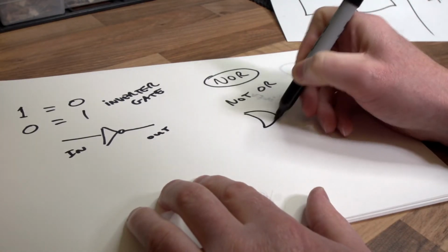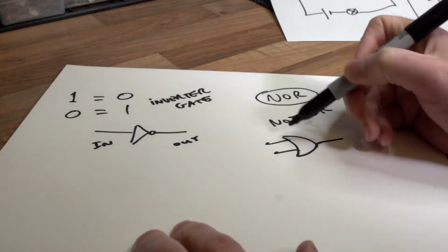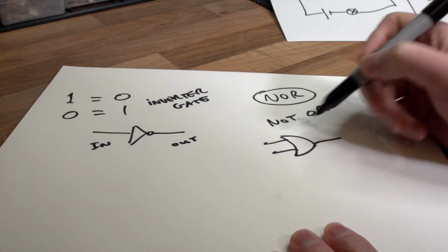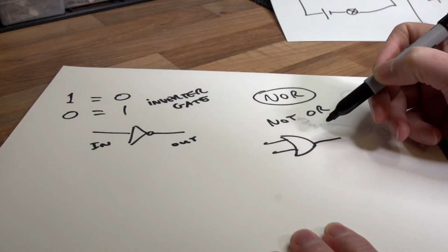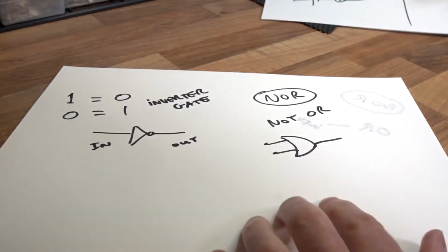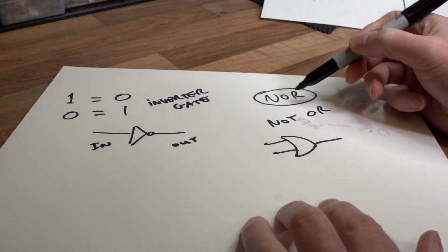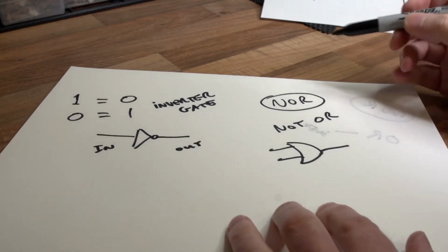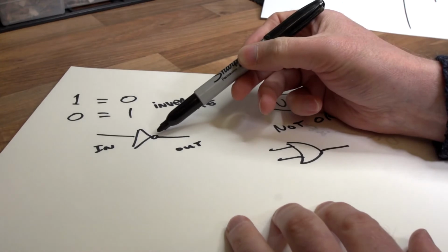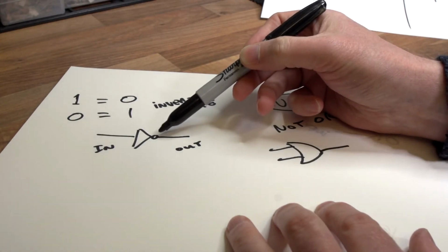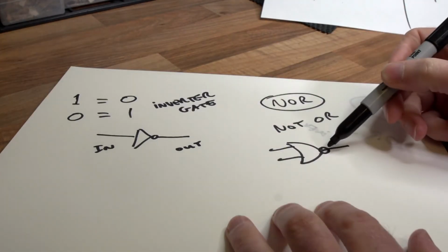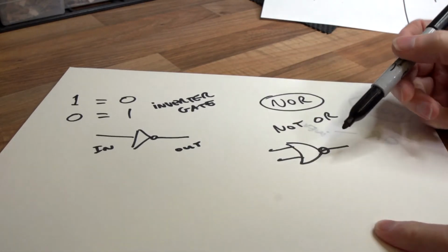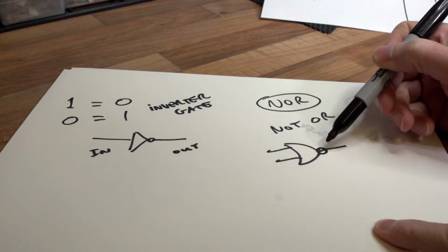Okay. Now if you were to look at the electrical symbol of a NOR gate, it basically looks like that. That's an OR gate. It has a curved front usually on the front of it. So it has a curved input. That would be an OR gate, like what we're showing here, but we want a NOR gate. Now to invert it, or not OR it, if you're with me, hope you're following this, we need to do this and put the little circle on the output. That inverts the output. So that circle means invert whatever you would normally have had. It's an OR gate, but we've made it into a NOR gate by putting a little circle on the output.